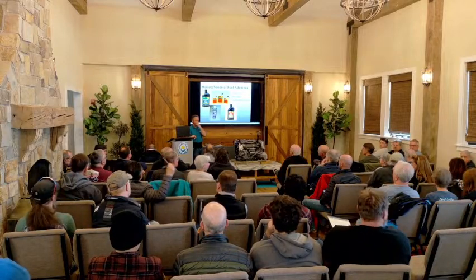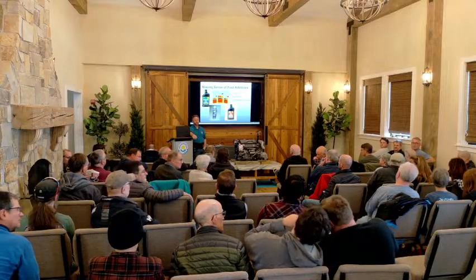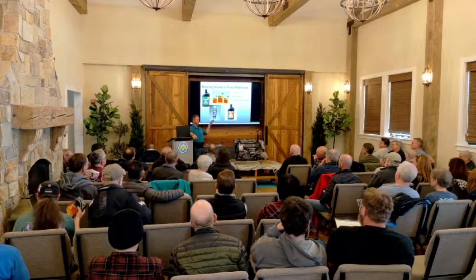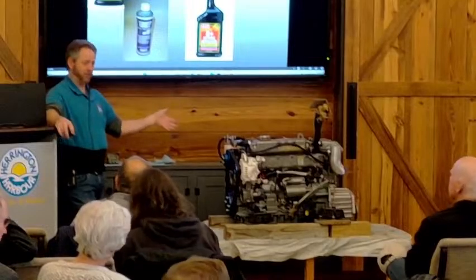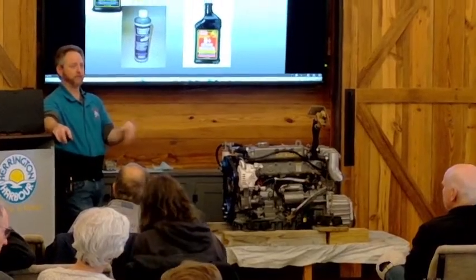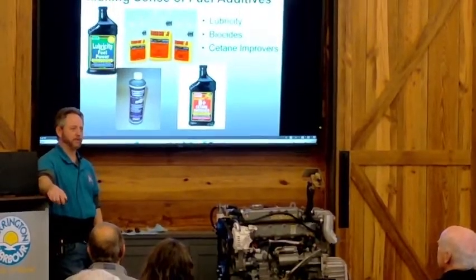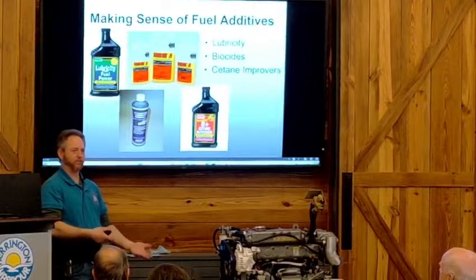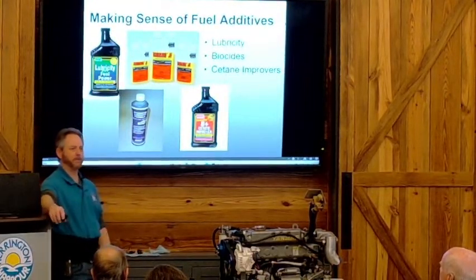I just want to make sure I heard you. You say usually the cetane is okay for like 18 months? If your fuel tank has not had any fresh fuel added to it in 18 months to 2 years, then you may want to put some cetane improver into it. But if you keep putting half a tank every year back on top of your old fuel, you're bringing the cetane level back up every time you put fresh fuel in.